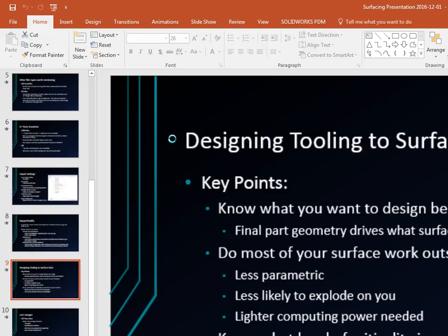Quick question. You've got those, you copied the little top parts of those surfaces. Yep. So the smart thing to do, since those are curved around, would be to extend just that surface away from the part a bit before extending and joining, so that you make sure you don't have any weird join points right at that surface. Yeah, probably. That's a good point. So extend them first.